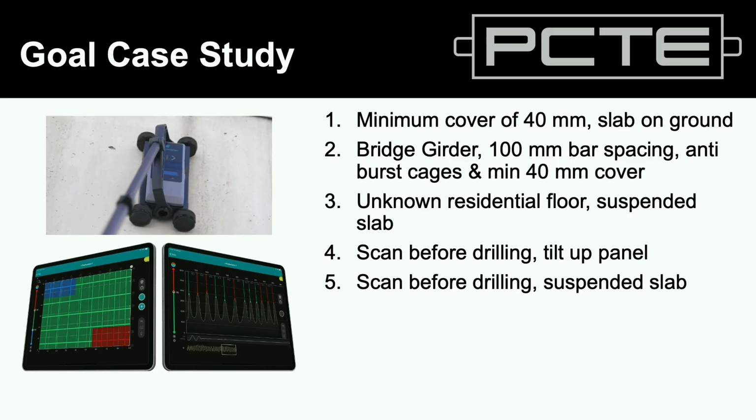it's there. The other thing is there's quite a severe depth limitation on cover meter surveys. They go 150 millimetres, barely the thickness of a pretty naff slab on the ground. You're going to want to use radar for the additional depth penetration, the additional sensitivities, and the ability to locate multiple layers of targets and multiple types of targets, including non-metallic.